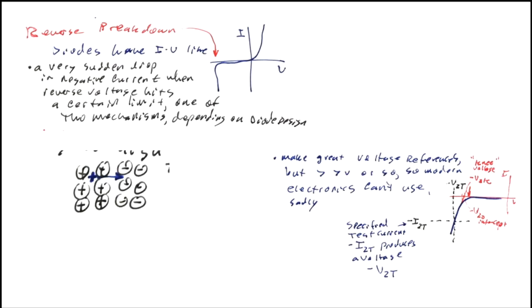And so the more and more voltage you apply, the more and more covalent bonds you break, and the more current you get. And it happens very suddenly because there's a characteristic energy for most of these covalent bonds. When you hit that voltage, they all start breaking down, and you get this massive current right away. And that's the Zener effect. And there's usually a combination of the Zener effect and the avalanche effect.